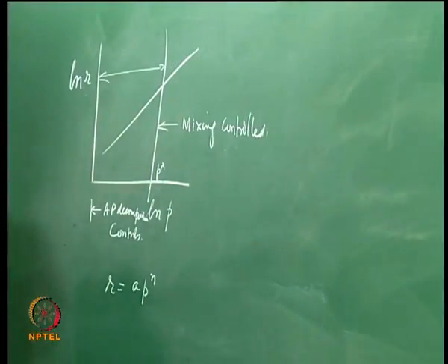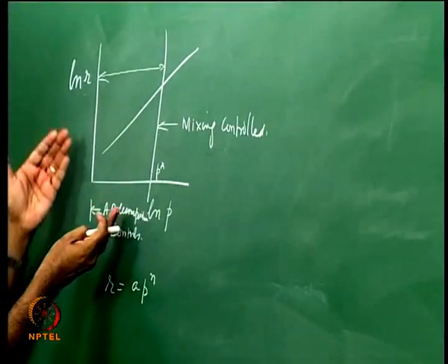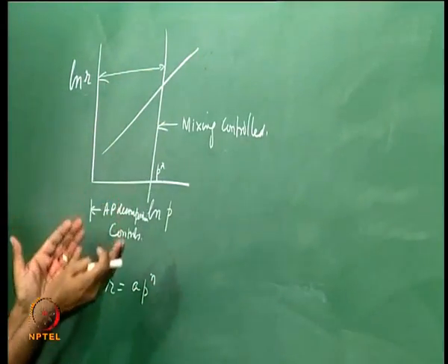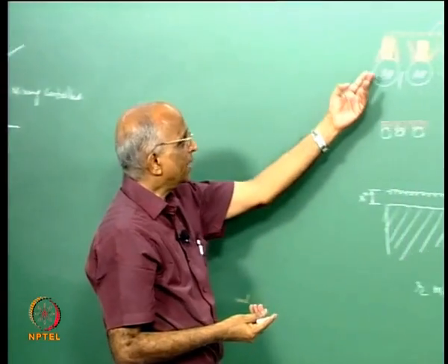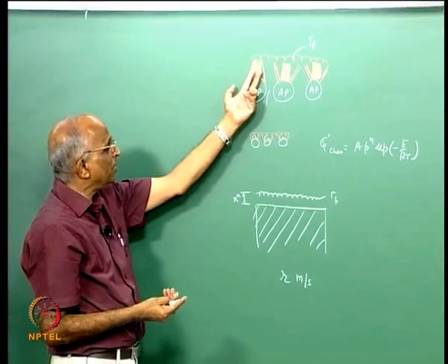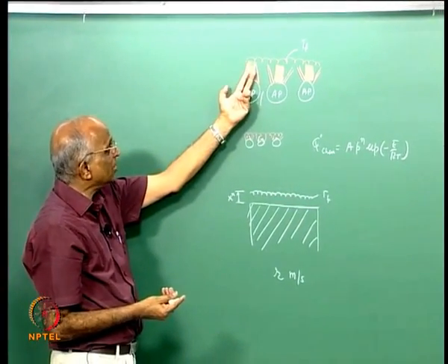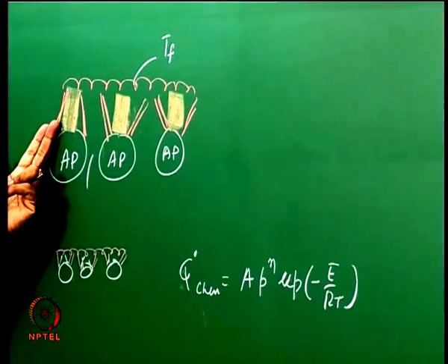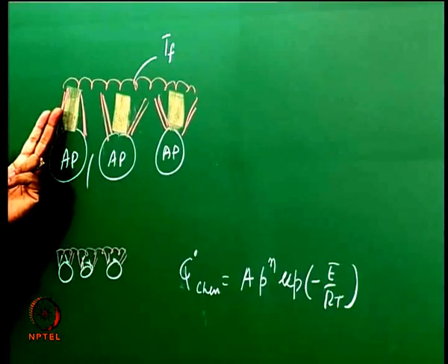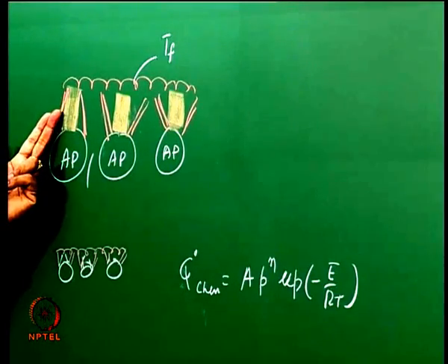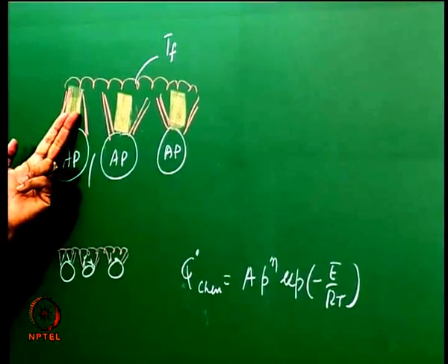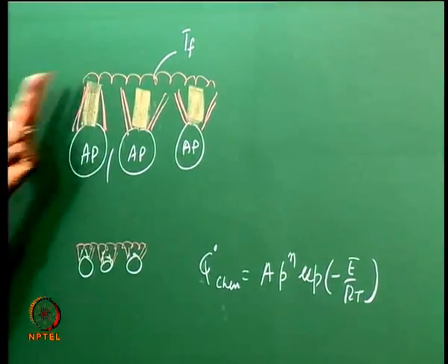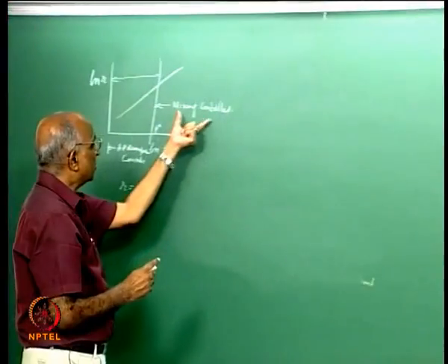All I am trying to say is, normally I would get the same n over the region, this is what I was expecting, but the phenomenon is changing. At low pressures I get premixing or premixed flame dominating, or this is the limiting factor which controls the final temperature, whereas at very high pressures diffusion is less, and therefore since it is less it becomes the controlling factor, because this is available to you but this is not allowing the availability to get back into the final temperature, and therefore I say it is mixing control.